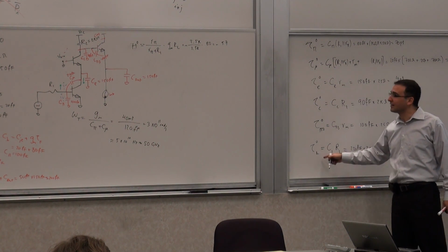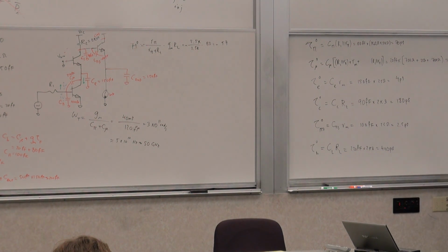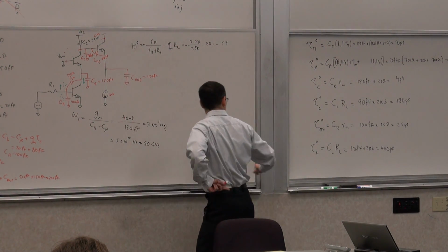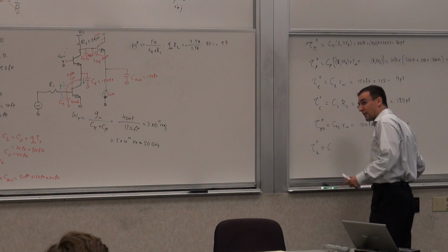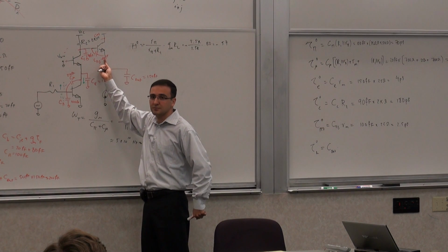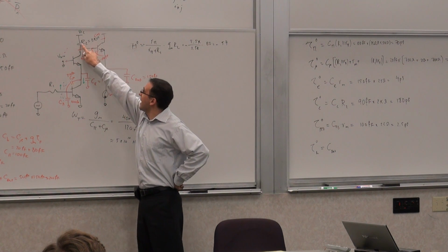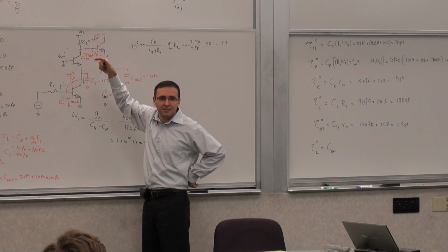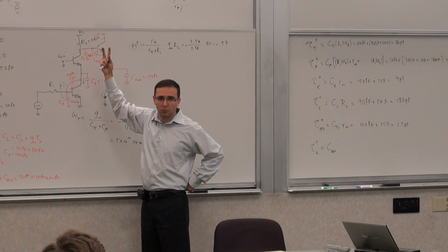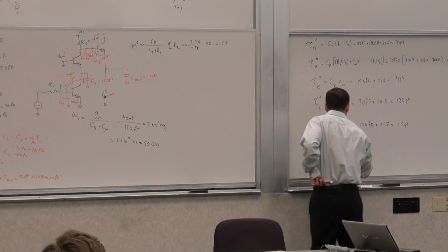And now how about my tau L? It better have changed, right? I mean, we did all of this for tau L. We introduced all these new time constants. So what is a new tau L? Well, it's C out, in this case it was 440 picoseconds, remember, times the resistance. What is the resistance you see looking up here? R2 over beta, the reflection, remember the reflection, right? It's this guy reflected down here, divided by beta plus 1. So it's 2 kilo ohms divided by 100, which gives me 20 ohms, plus Rm, which is 25 ohms, so it's 45 ohms.